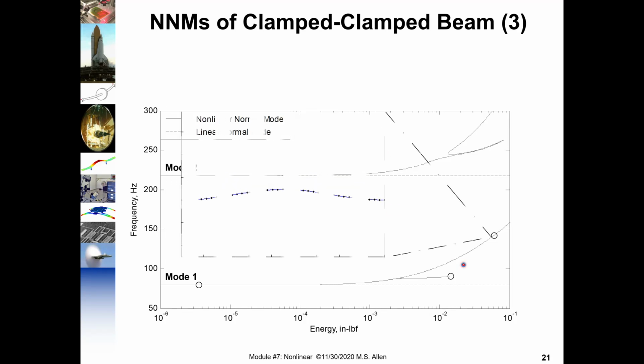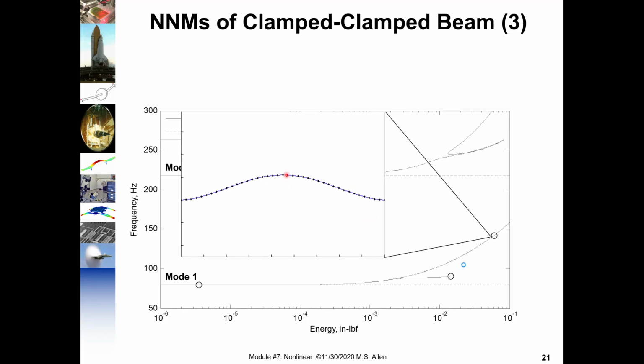Let's first look here. At really high amplitude, we get something very similar. But if you look really closely, you can kind of see the shape flattening out in the middle due to the stretch, due to the nodes having to move both laterally and up and down. And the beam is really stiff laterally, so that causes a big increase in the natural frequency.